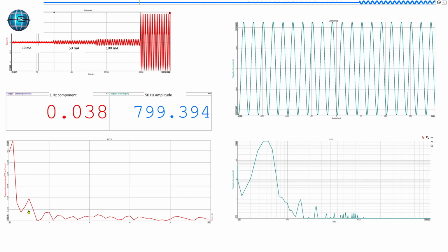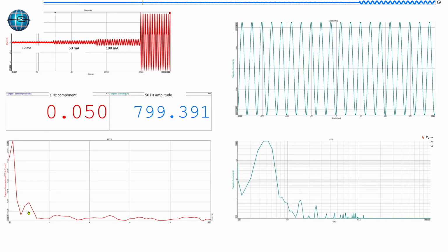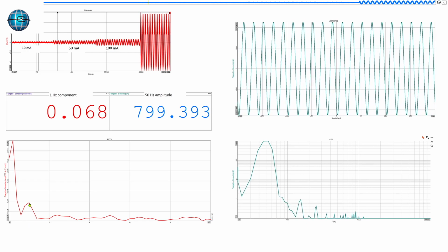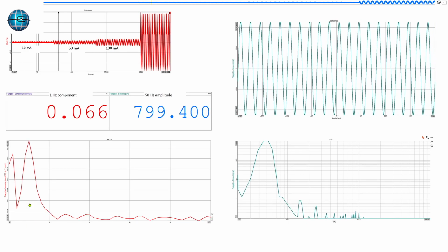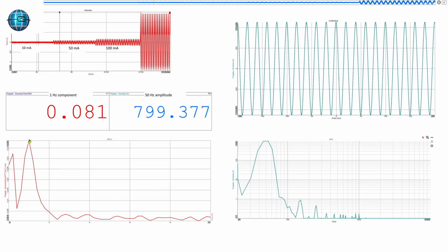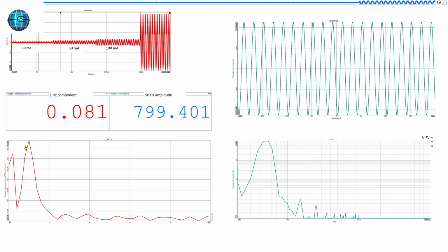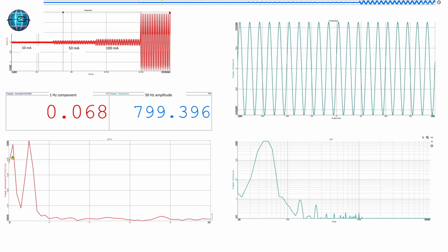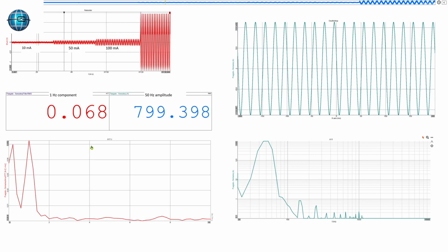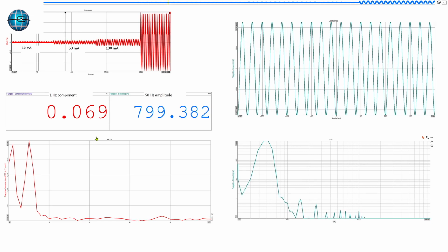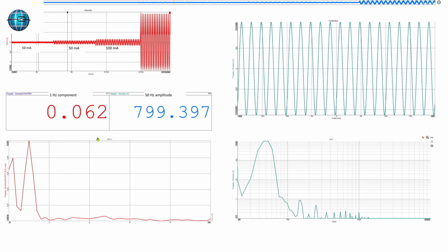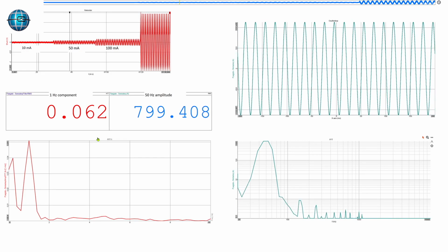Here we can see, now have a look at the FFT analysis. There should be now a bigger 1 Hertz component. Yes. It took some time, but we now see the big 1 Hertz component here, and we still have a DC offset in this measurement. So it would be good if you have a power quality analyzer which can compensate the DC offset in those measurements, because then you can be more precise.